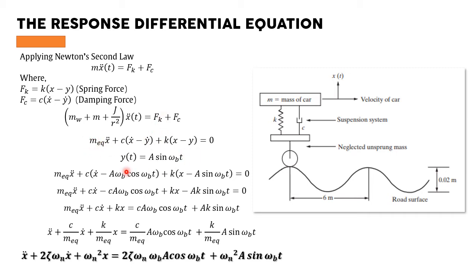We have just solved this, and additionally, you can see the bumping of the road, which we have treated as a sinusoidal function. We assumed the trend follows the form A sin(ωt), where A is the amplitude of this wave. We simplified by keeping the y values here, and by changing c, the damping coefficient, and k, the spring constant, into ζ and ω_n, the natural frequency.